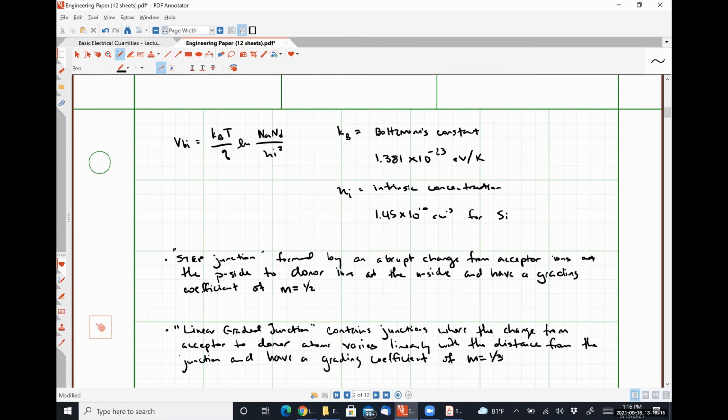The level of concentration tries to balance itself out in that region, because that's what happens in diffusion. So you see the concentration gradients, instead of falling off abruptly, are a linear change as we move across the junction. This is much more often what you'll actually see. So really, it should have been under a cubic root sign the whole time. But anyway.